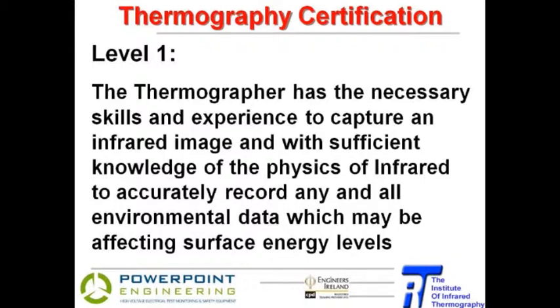So level 1, we're assuming that the thermographer has got sufficient skill and experience. They know how to use the camera. They can capture a good image, and they can take into account any environmental data that may need to be recorded to attach with that image. Because if somebody presents you with an infrared image without the environmental data, that's all it is. It's just a picture. So unless you have the environmental data that goes with that to explain what was occurring at that time in terms of weather conditions, if you're doing an electrical survey, what were the load conditions at the time of survey? So level 1, able to acquire a good image and record any data.